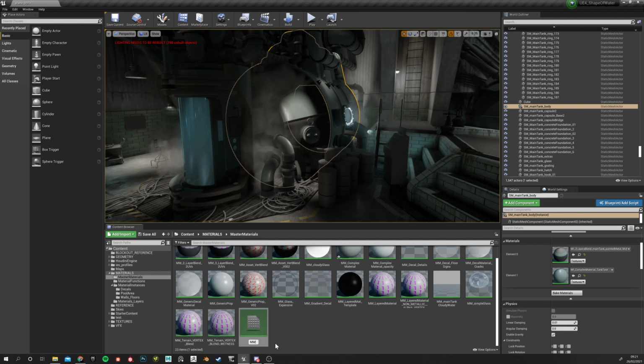I'm trying to follow that. Things like particles start with P underscore. Even with the new Niagara, you have Niagara System NS or Niagara emitter NE. That's always good because you can type the prefix here and it will automatically filter out everything in this folder. You don't have to go and search, so it's easy to find things.